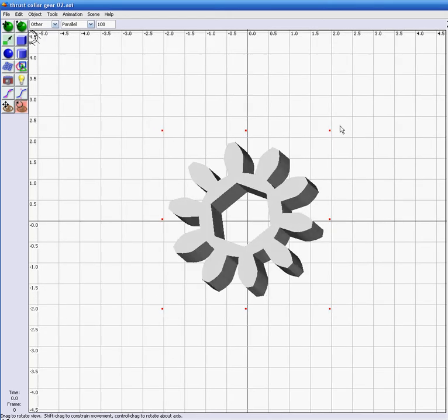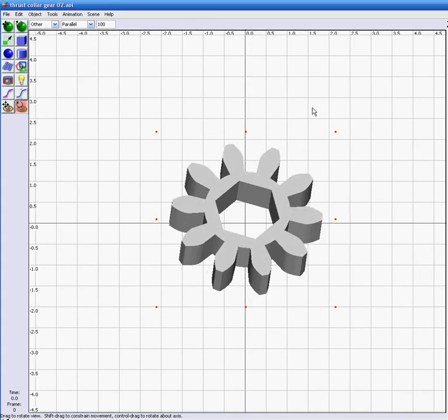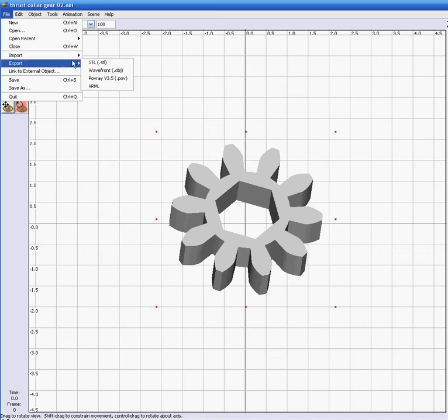Now, when you're going to print an object, this is what you do. This is what you have to have. You have to have the solid object. Then you export it as an STL file. You crank it into what I call slice and dice software, which slices through it, and then traces paths for the printing of the plastic over those slices, and then you just print it.